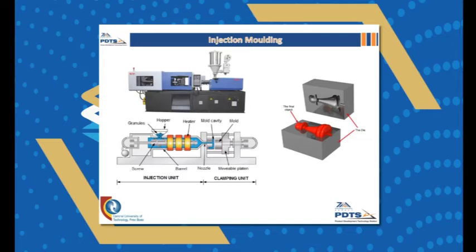So a mold is actually two metal blocks which come together, and on the inside there is a cavity of the final part. These molds can either be manufactured from metal blocks or plastic, if you would like to do so. The metal blocks are mostly manufactured using subtractive manufacturing processes. And this is where that large monetary risk comes in, which we talked about earlier.